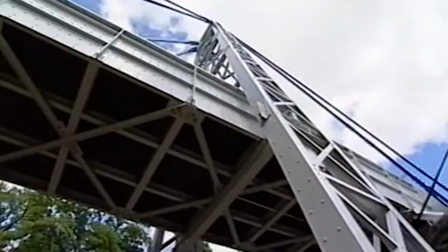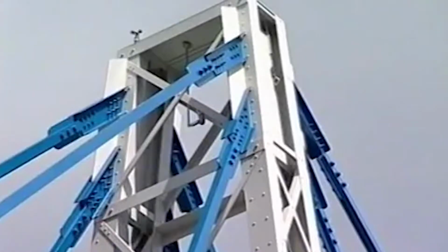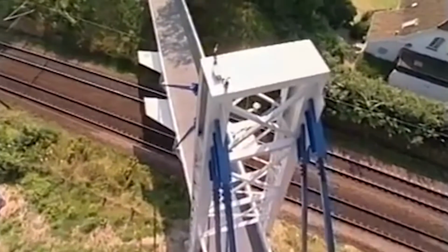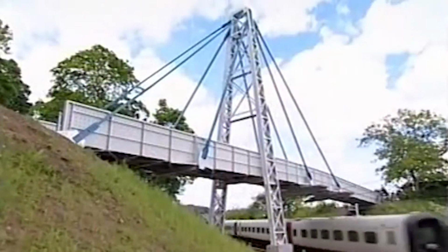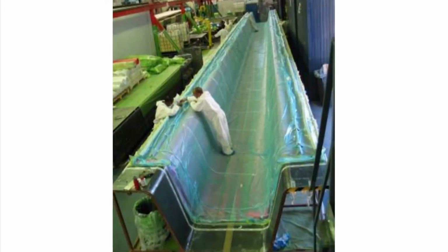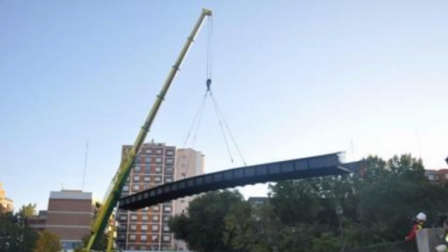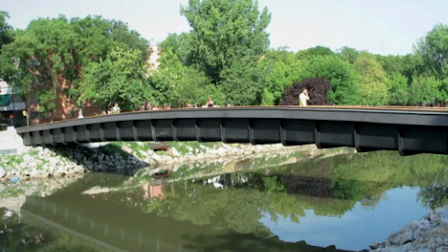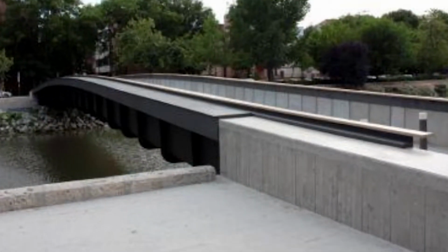These bridges are fabricated from FRP components and often joined together off-site and delivered to the site in a completed state. Some bridges are fabricated in one piece the same way as boats by layup molding and then delivered in one piece to the job site. The extreme lightweight properties of FRP allow these large structures to be easily delivered and placed.